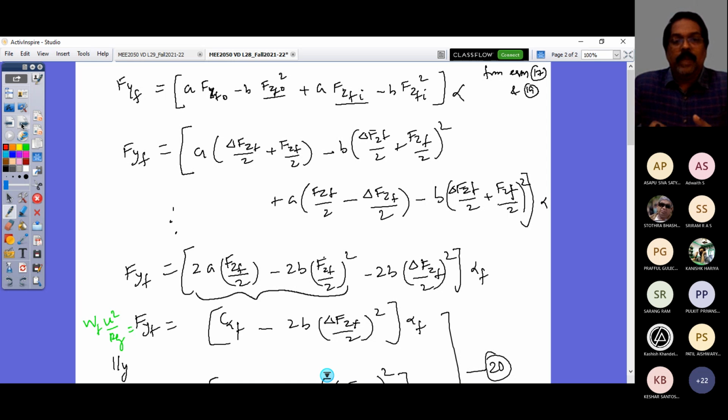We understood very well that the bicycle model is a nice, sufficient model for lateral dynamic study. But in a real-time scenario, to represent your vehicle, particularly in hard cornering, to study its lateral dynamic aspect, we have to consider also the suspension.